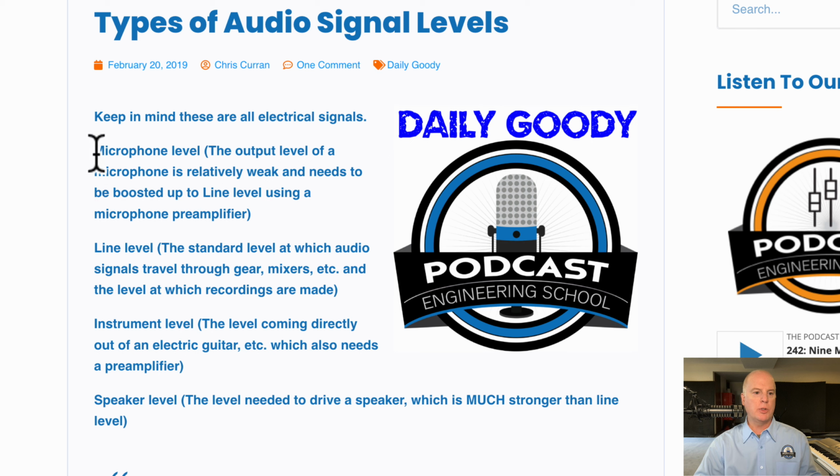So the first one we'll talk about is microphone level, and that's the output level of a microphone. Microphones have relatively weak output levels. That's just how most microphones are made. The signal that a microphone creates is not strong, it's weak. And so it needs to be boosted up using a microphone preamplifier. So that's a preamp. You need to boost the microphone level signal up to line level.